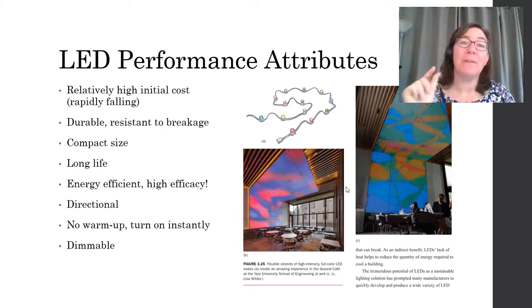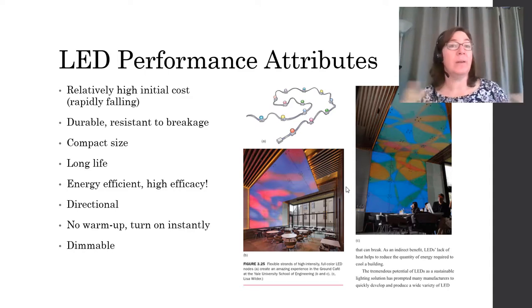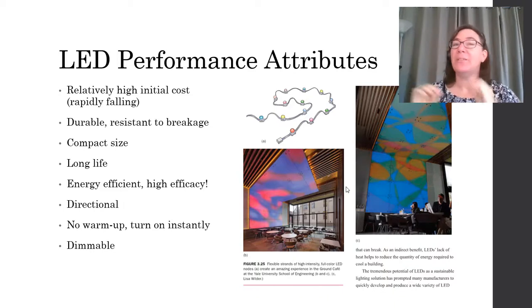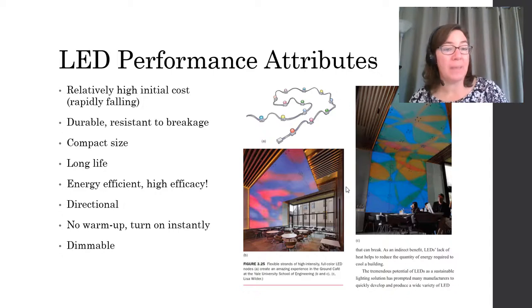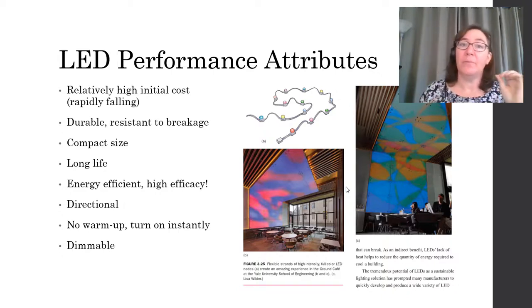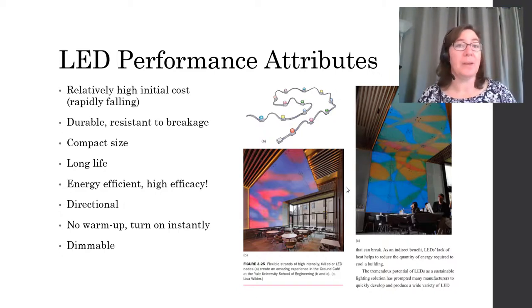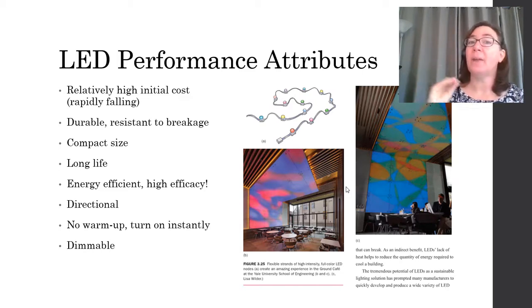LEDs are very, very small. They are compact in size. They also have a long life. They are extremely energy efficient, meaning they have high efficacy. LEDs are extremely directional. They have no warm-up time. They turn on instantly. Fluorescents have gotten better. They used to have a longer warm-up time, and there are some other lamp options that have significant warm-up time. And finally, and this is very important, LEDs are dimmable.